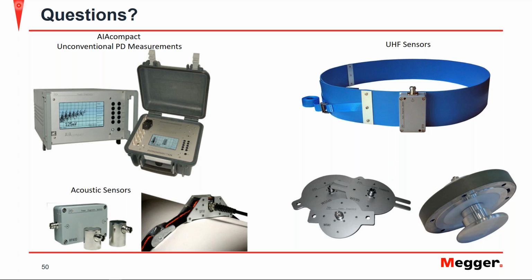Okay, thank you for that question. They are, but not entirely. So we have to look out for slight differences in there. If I record a PRPD in UHF or according to IEC 60270, it doesn't make a difference when I look at it first, because the form and the shape of the measurement that I'm seeing in the PRPD looks pretty much identical. However, there are some important differences that have to be considered, and that is especially the measurement on the y-axis of my graph.